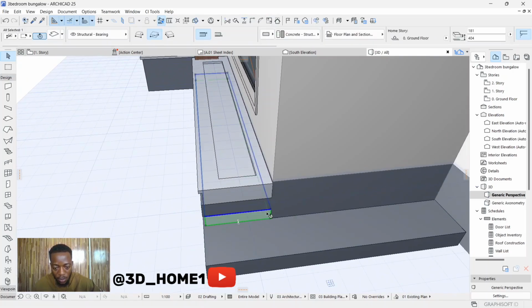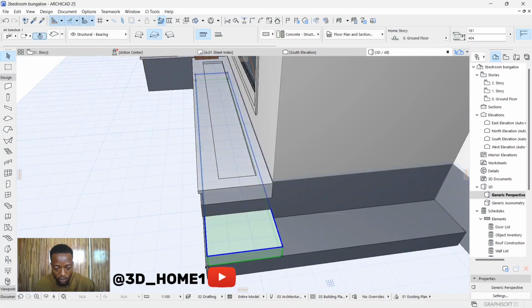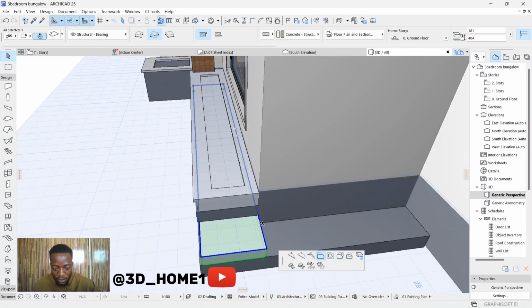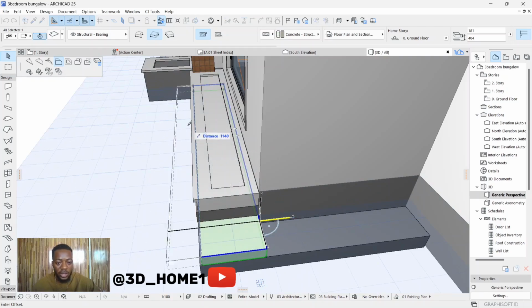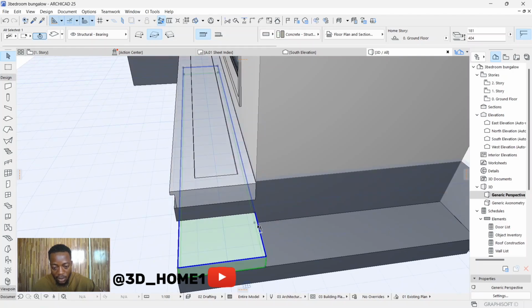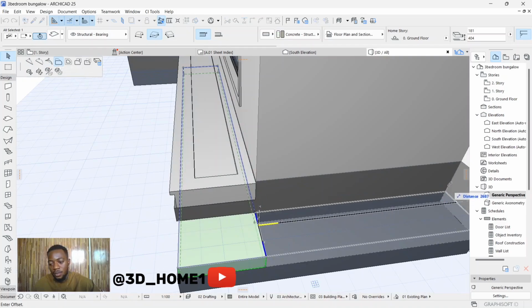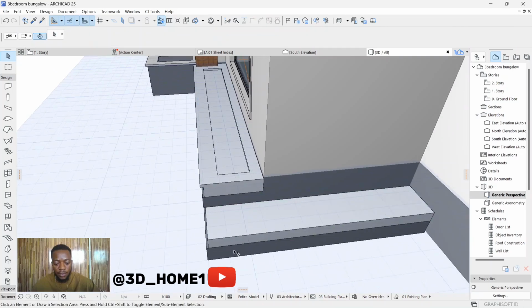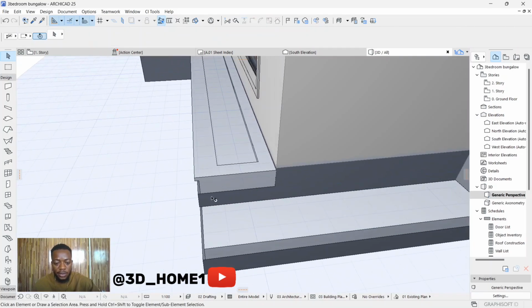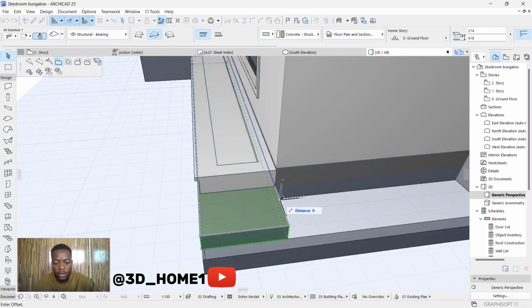Okay, let me do it on this second one. I'll drag here, align it to this point, then I'll click this blue line as if I want to drag this one. If I drag, it will drag everything, so I'll just click on insert new node, and then I'll take it back to this first point, and then now I can drag this one by clicking on offset H to this point. Don't worry, I'll shift this one later. So now the same thing, I'll highlight this one, bring it here, I'll click here, select new node.